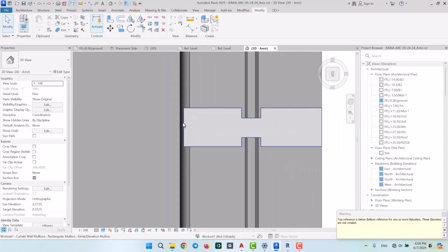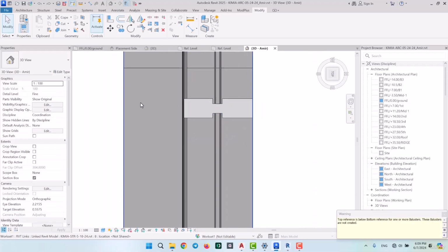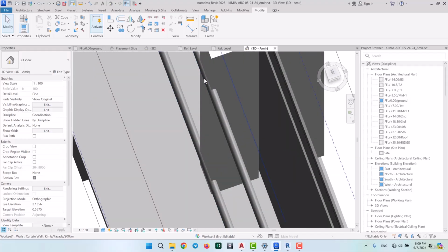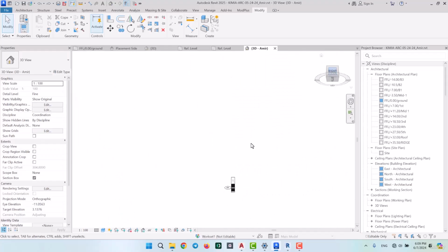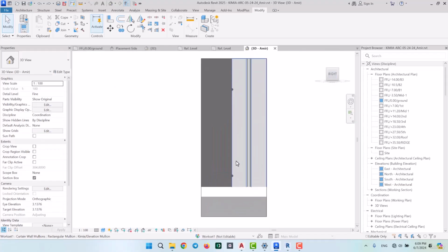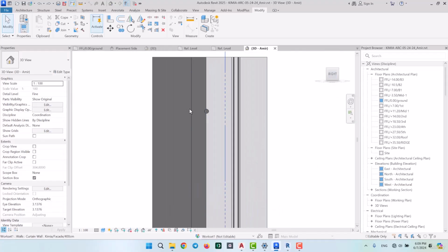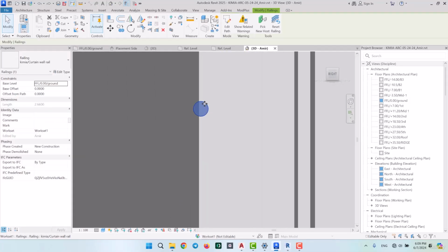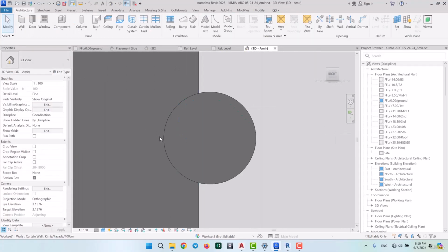When you come across something like this, you're going to have to actually assign an offset to your railing, and it's going to back up a little. And that applies to all the other railings you'll draw. So for instance, if I try to view this railing from this angle, you will see it right here. Here's its profile. And so we're going to need to measure this amount and give it an offset by that much, so it'll back up from the mullion.